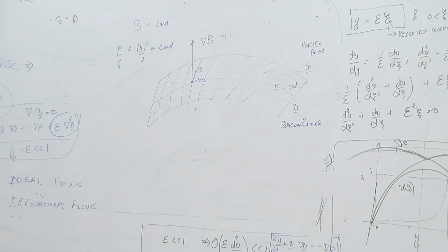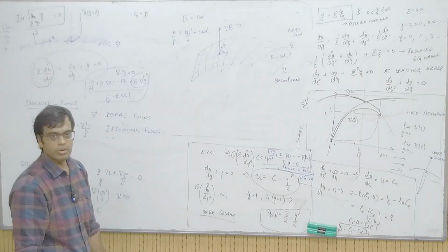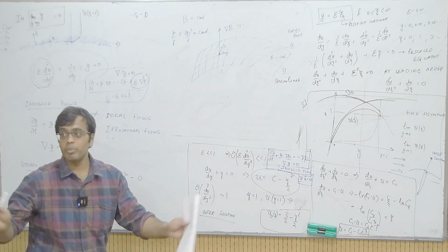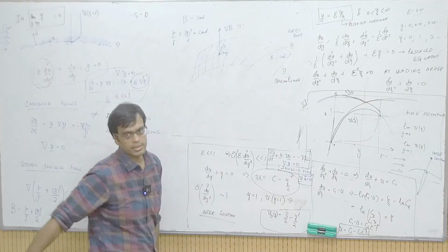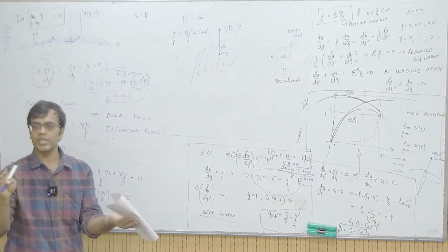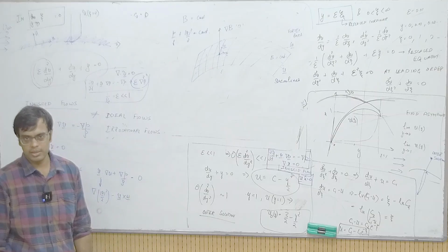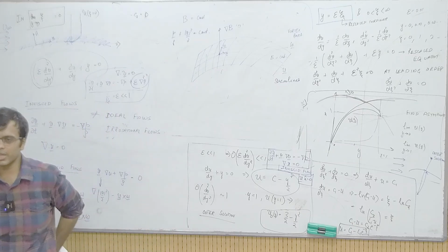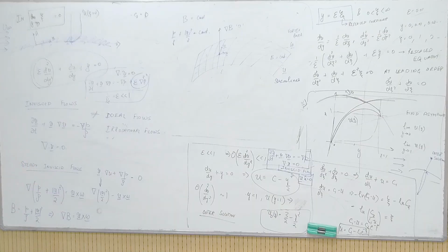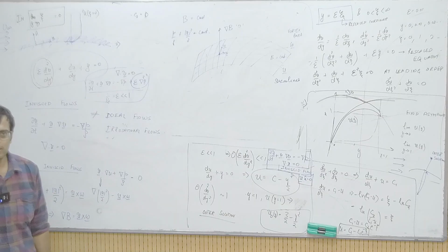Okay, so your Bernoulli's equation, which we tend to apply everywhere, is applicable only for steady incompressible inviscid flows, always in this course. That is when you can apply Bernoulli's equation, not between any 2 points, only along streamlines or vortex lines, or on the surface defined by streamlines and vortex lines, which is a very contorted way of thinking about these things. In actual fluid flows it will be just easier to visualize streamlines and apply this across 2 points of a streamline. Okay.